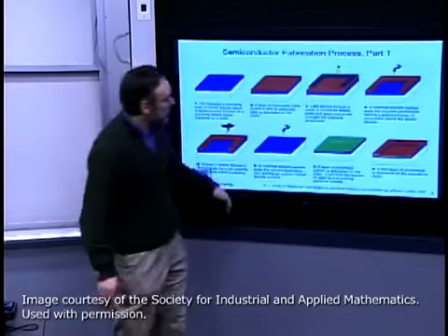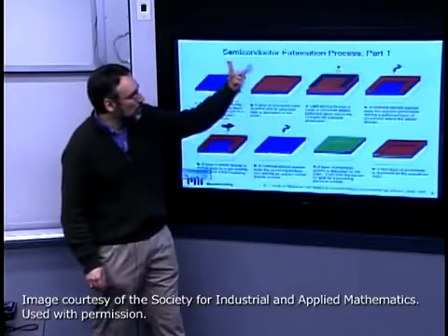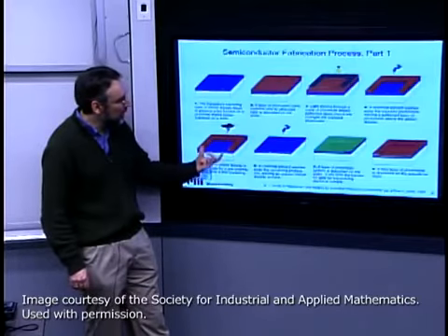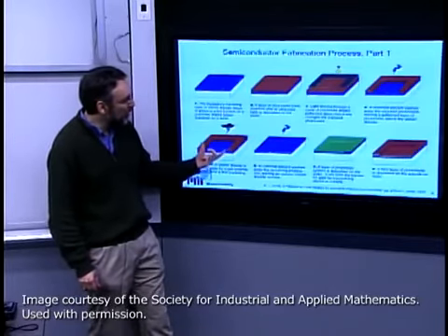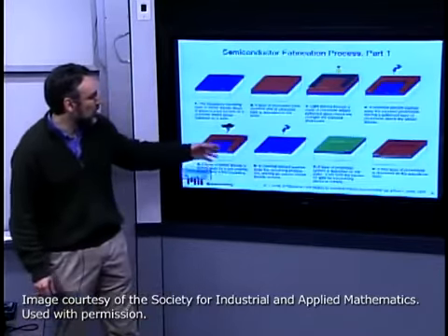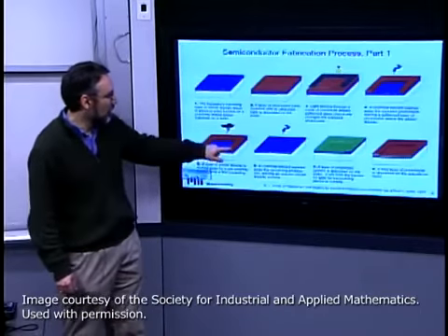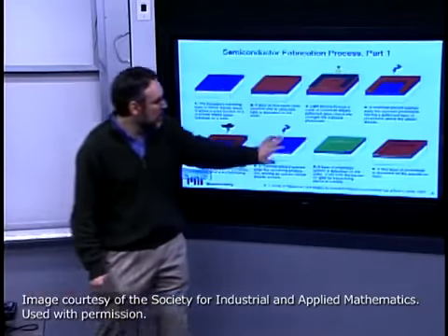I remember that one. I think there's another one someplace. But okay. So still sort of taking this at face value, we had the photolithographic sequence that imprinted onto the photoresist. We used that then to controllably change the permanent structure, the silicon dioxide, and then we remove the temporary photoresist using another chemical solvent, or in many cases another plasma etch, a plasma ash. Okay. Then we go on.